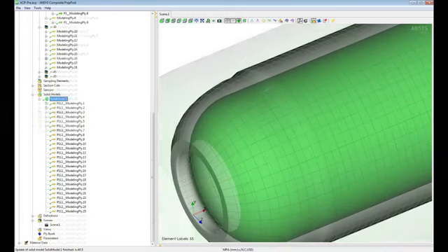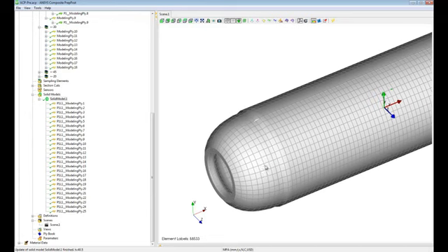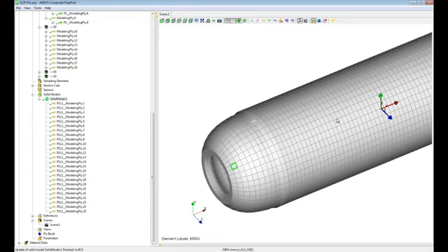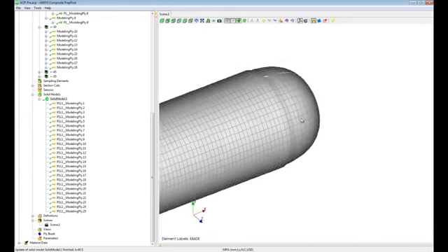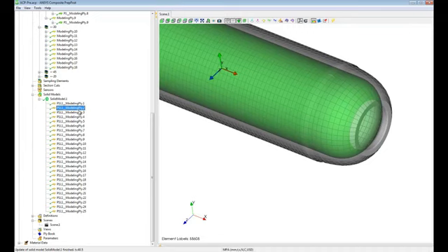So we are using a couple of geometric guides to make sure that we follow a given geometry, and we are extruding all the plies to create a 3D model made of hex elements and some wedges in the drop-offs that we are going to reuse when we assemble them with the caps that we have defined in this second model on our project page. And here you can review each and every ply within the 3D model, obviously, as you could do on the shell model.